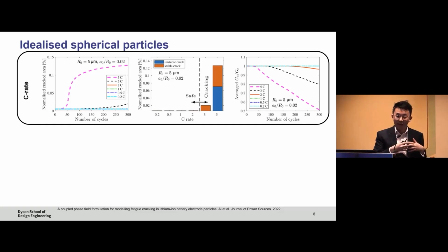And then you also have more stable crack growth, which you might get in more plastic materials, where if you've got a polymer, you can see that crack growing very slowly. And what causes this nonlinear behavior is this kind of degradation in the fatigue strength of the material. And we can describe that with our phase field models.